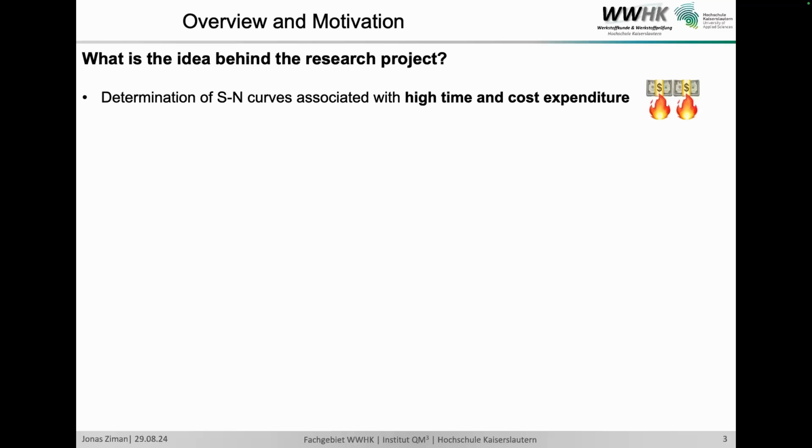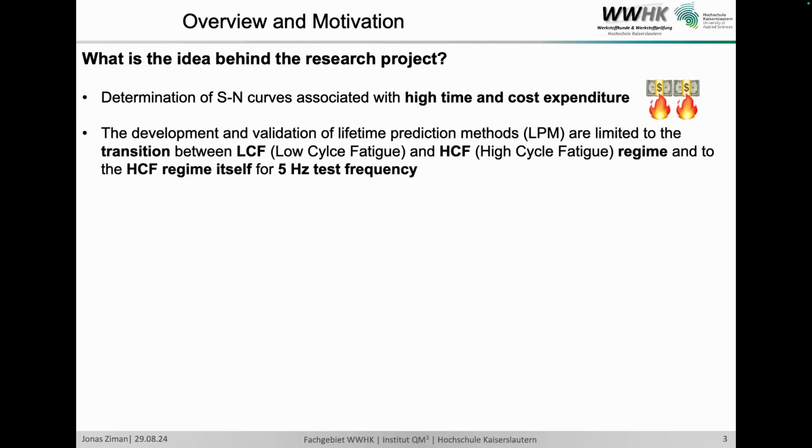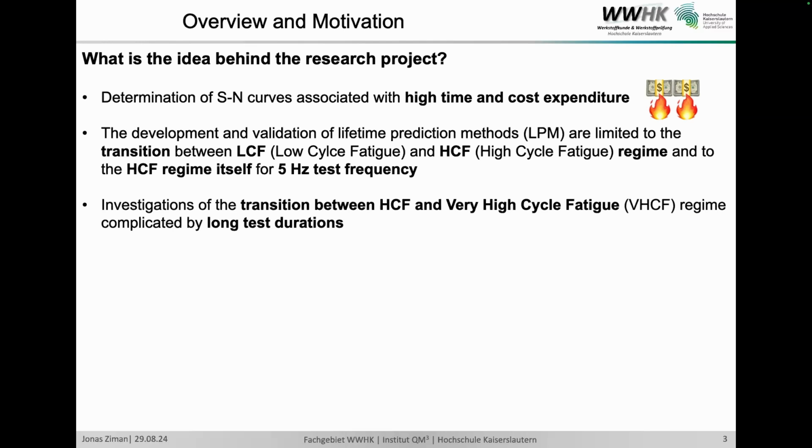But the problem with those lifetime prediction methods is that they are often limited to the transition between the low cycle and high cycle fatigue regime and to the high cycle fatigue regime itself, and for test frequencies of a few hertz. Therefore, investigations of the transition between the high cycle fatigue regime and the very high cycle fatigue regime are also complicated due to the long test durations.